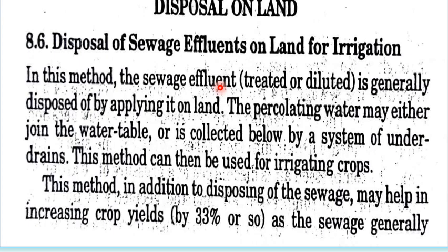While moving, what happens? A huge amount of sewage is absorbed by the ground. It is the infiltration process; it will go inside. Most of the water will be absorbed by the ground itself. This water continues until the flow becomes zero. Surrounding open wells absorb this, and everything becomes part of the groundwater body.